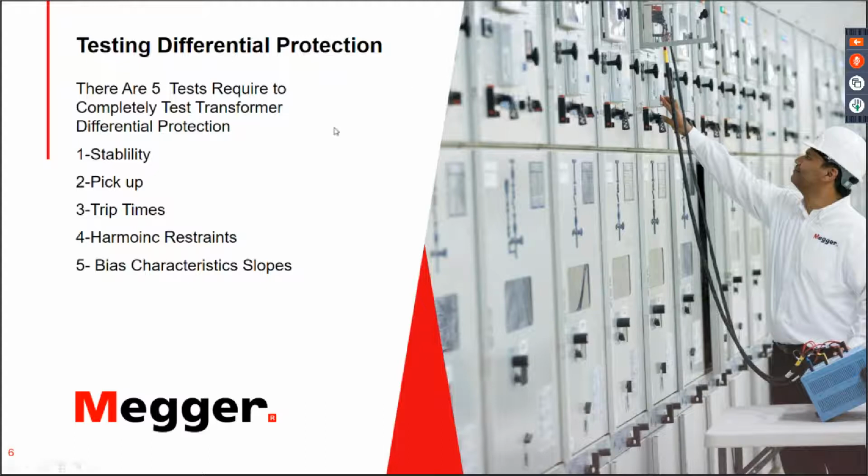Then there are pickup tests, where we test the start of operation according to the differential current. Also, we will test the trip times. I know I have mentioned that the operation of differential protection is usually instantaneous, but in real life, there is no such thing as instantaneous. There will always be a slight delay. We will test that and see how much that delay is, and whether it is acceptable or not according to my requirement.